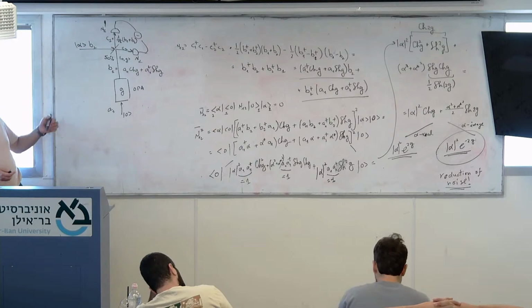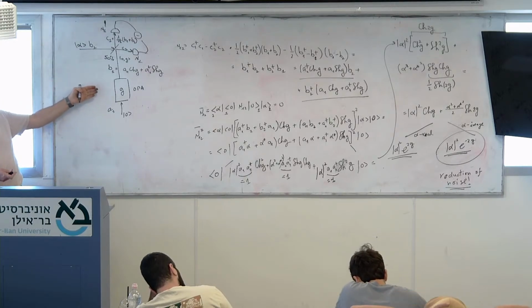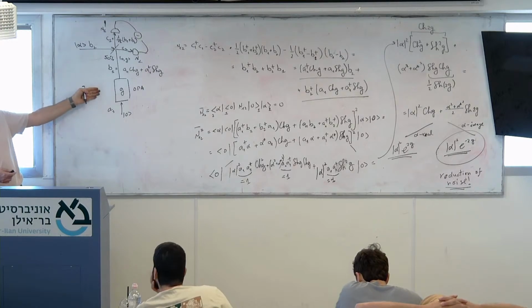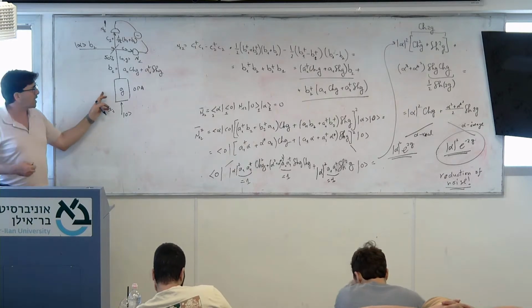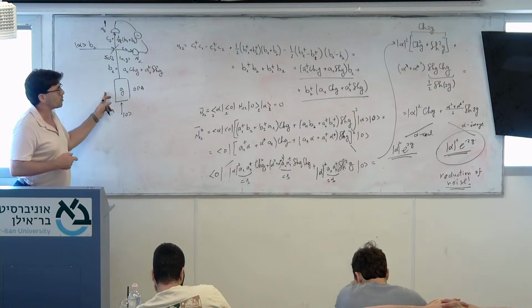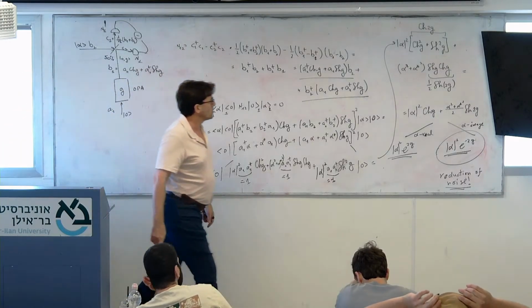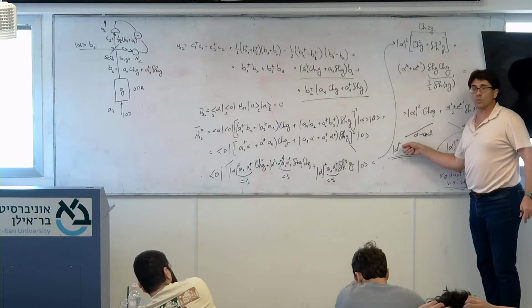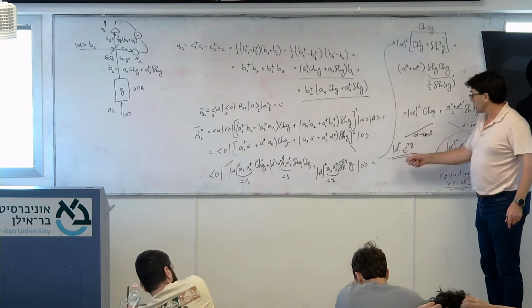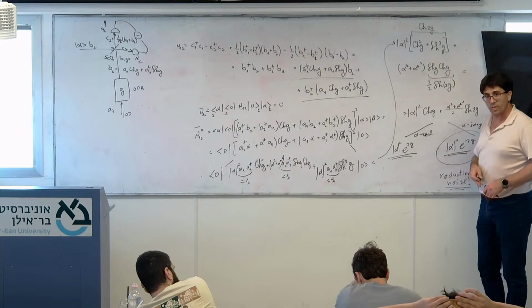It depends on the phase of the local oscillator, or if you want, it depends on the phase of the gain. The parametric amplifier can also have a gain that is a real number, but it can also be negative. If the gain would be negative, then the minus sign will be here. And then, of course, this will be the one that is diminished, and this will be the one that is amplified.